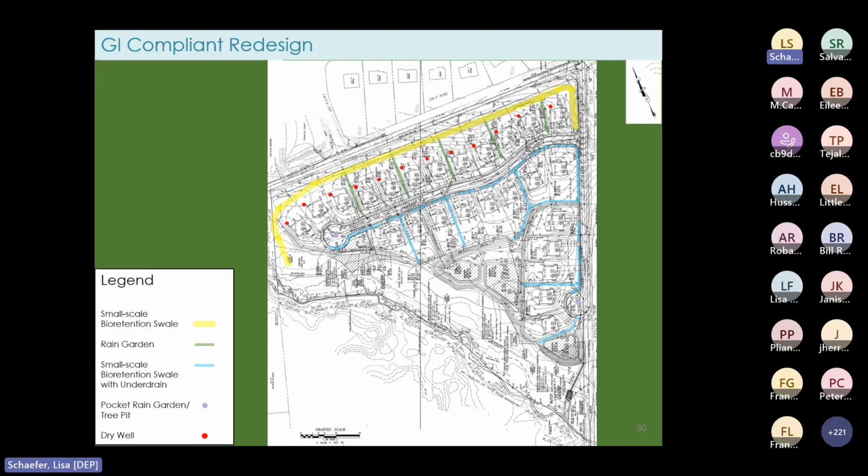All right, now I didn't really go into the groundwater recharge for this site because everything was underdrained, but in this instance, the recharge spreadsheet would probably be the way to go to determine the deficit created by the proposed design. All right, now, if you remember, some of the areas had depths to the seasonal high water table of 5 to 6 feet below existing grade. And by using shallow vegetated planting areas along the road to the east where fill is proposed, plus the dry wells for the northern homes, they're probably going to be enough to address that deficit.